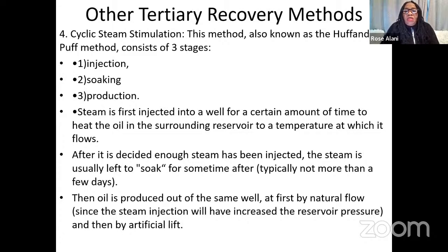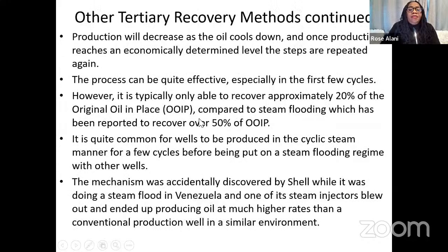So it can soak for not more than a few days. Then oil is produced out of the same well. At first, the natural flow will happen on its own because after soaking, some pressure is built. Initially natural flow will happen, but then production will decrease as the oil cools down.